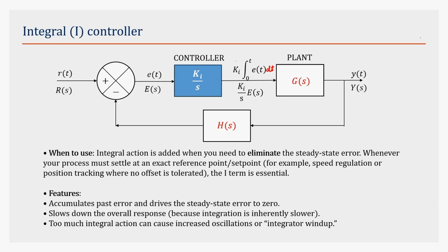We will see some demo examples also, then you will understand what I mean by that. So, we do not even need transfer functions in these type of scenarios. One problem is that, first of all, there is a tendency that if you increase the type of the system, the closed loop transfer function might become unstable, because when you are increasing the type of the system, open loop transfer function, you are introducing a pole at the origin, right.